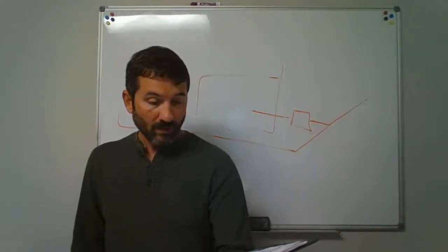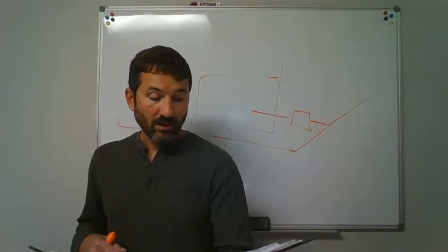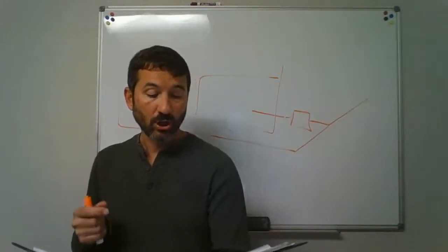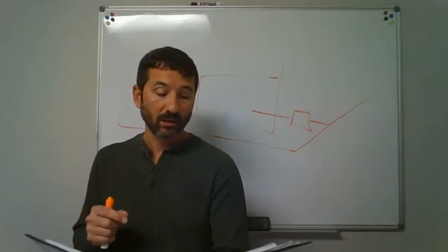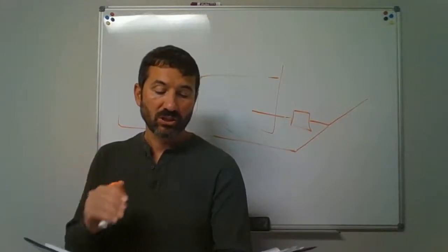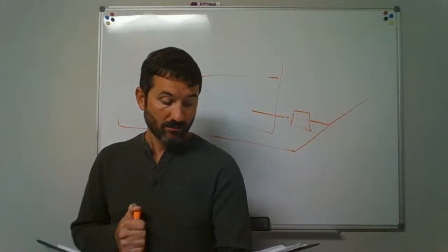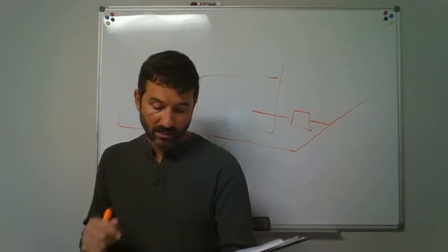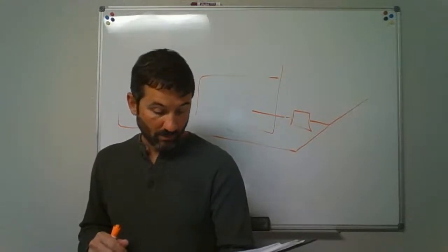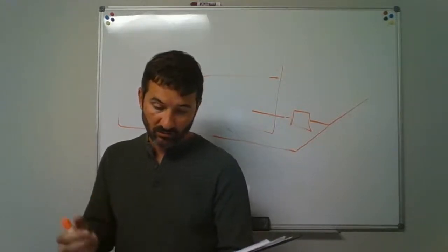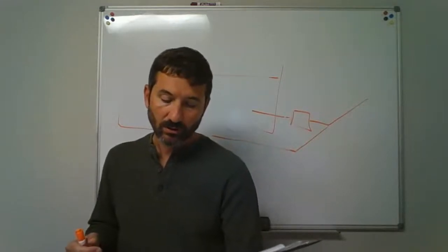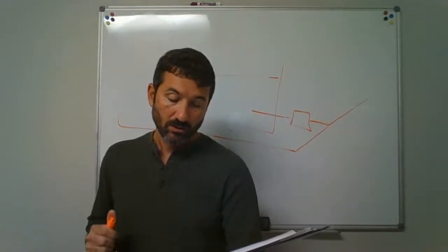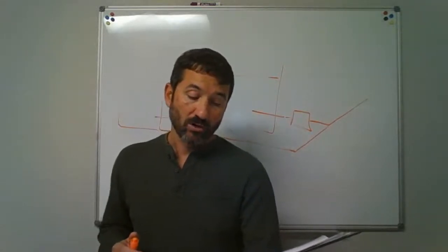All right. That table there is grease interceptor capacity, 1003.3.4.1. It gives you a total flow through rate in gallons per minute, and then a grease retention capacity in pounds. I'm going to let you read a good bit of the next section on your own, to save me from having to read that to you. If you have any questions as you do some of this reading, just let me know.